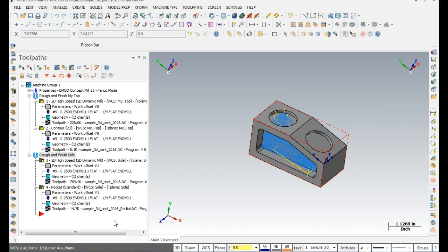Okay. Now, you just go finish it. Let's just do a pocket, do a high-speed pocket, and then do, I'm sorry, 2D high-speed dynamic mill, and then just contour. Don't leave any stock on the bottom, and just leave 50 thousandths on the outside, and then do a contour to clean it up. I'll let you do that.